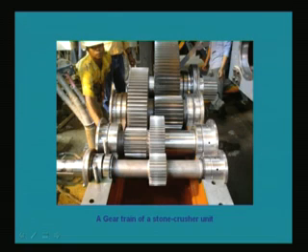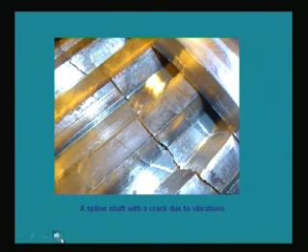So you can see these are the gears, and they are transmitting very high torque, and because of that their failure may take place, and they are quite large in number. So if any of these teeth is broken, we may be in trouble, because it will give a lot of vibrations, and because of that other members will also get damaged. One of the members which got damaged, especially this part, if you see, is the spline shaft. That view is in the next slide.